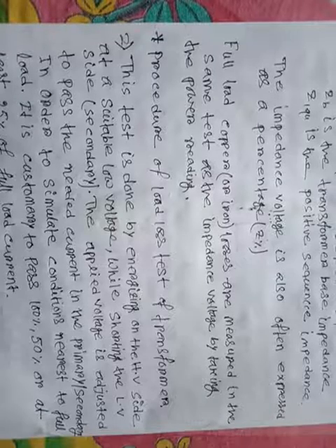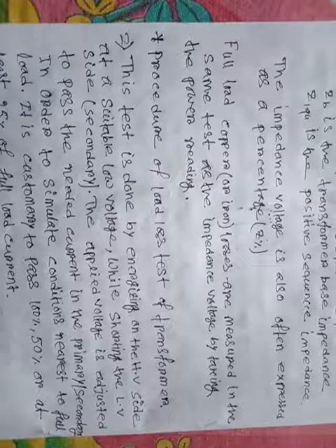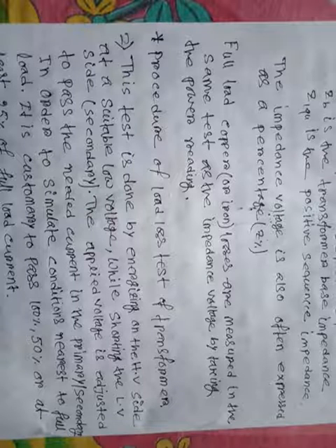Second topic is procedure of load loss test of transformer. Here there are two types, no load test and load test. The test is done by energizing the high voltage side at a suitable low voltage, while short circuiting the low voltage side, meaning the secondary side.